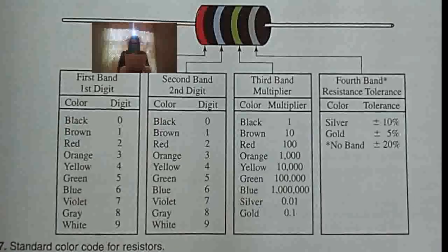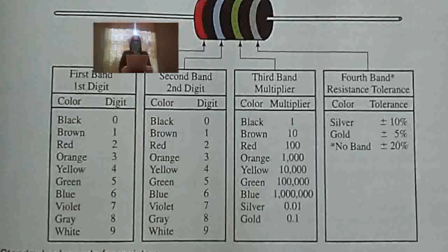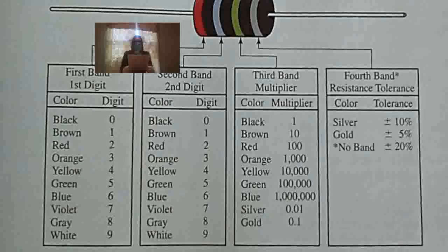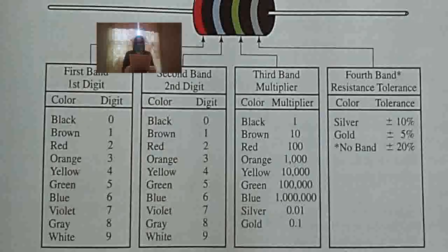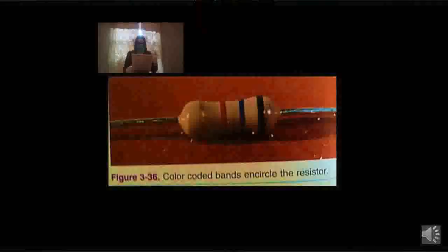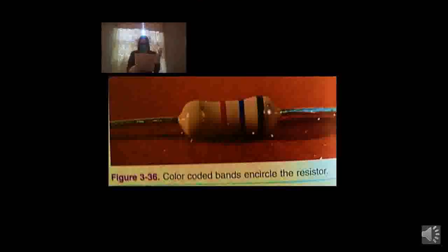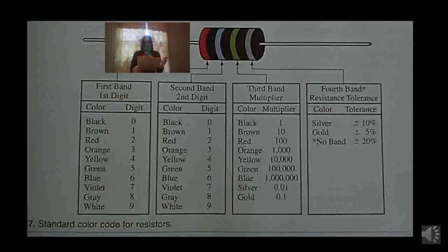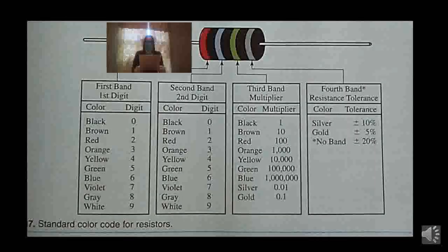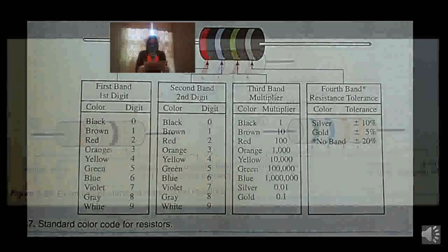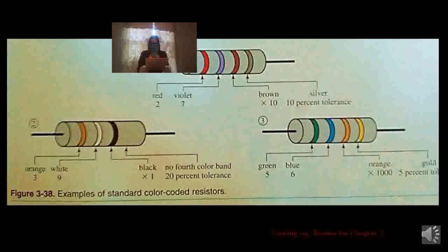When 4 digits are used, a tolerance of plus or minus 1% exists. For the 4-digit numbers, the same rule applies, that the last digit represents the number of zeros. For example, 5002 would represent 50,000 or 50k ohms, plus or minus 1% tolerance. For resistance values that require a decimal, a letter R is used to indicate the decimal point. For example, 7R5 would represent 7.5 ohms.